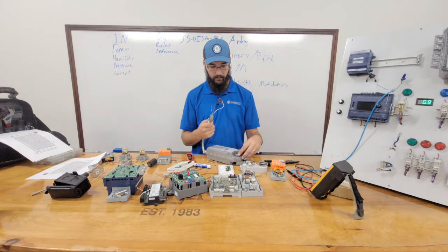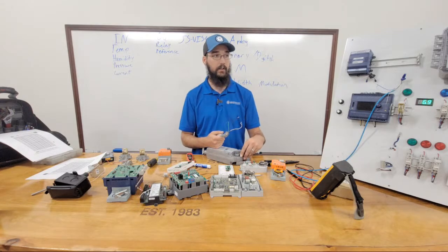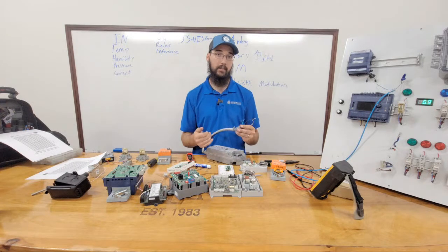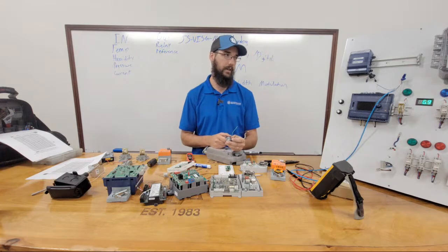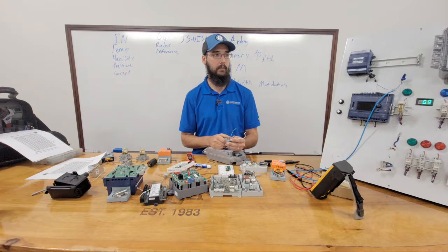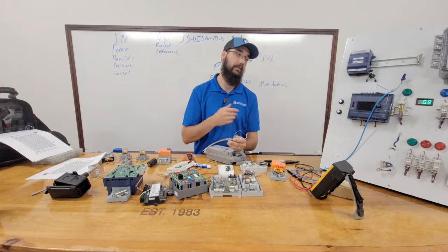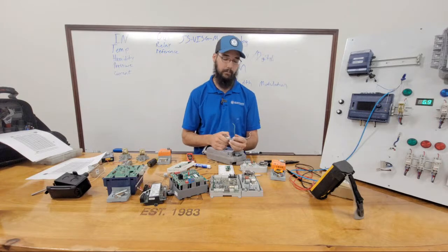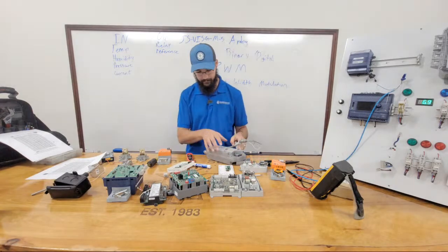And same way, if you have an outside air damper of any kind, I do recommend having some kind of spring return on that. Granted, some systems we put in now, we modulate that outside air based off of different conditions, but even if that was true, we're still going to have a true fire damper on that outside air input. Anyway.